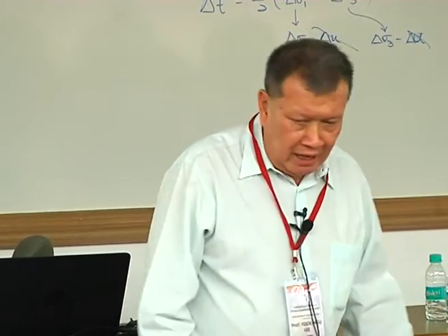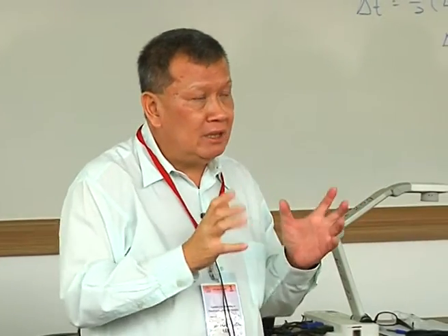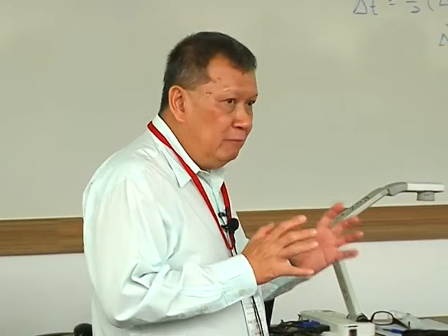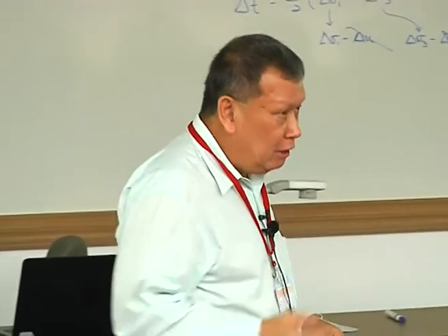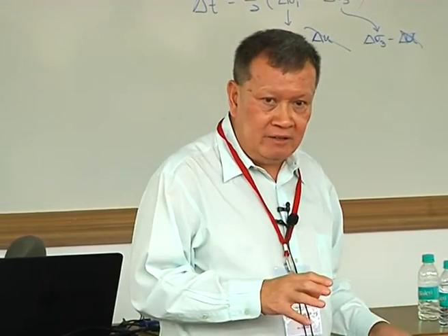So that's the nice thing about P, because if you express it in terms of principal stresses, it will be sigma 1 plus sigma 2 plus sigma 3 over 3. That is the mean normal stress. So the mean normal stress will automatically have the intermediate principal stress taken into account, whereas S, which is the MIT stress path parameter, will not have this property.